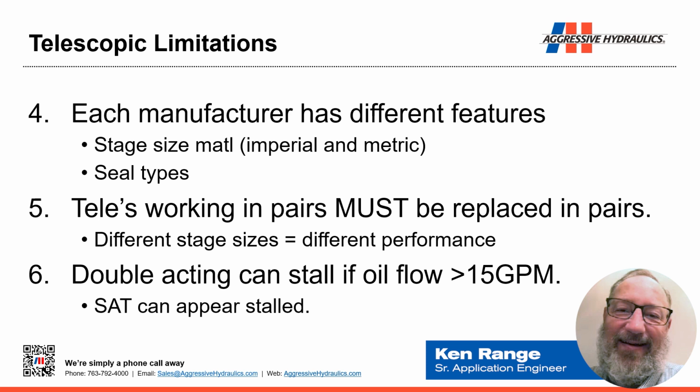It might only represent a few millimeters, but when you're talking about a very large stage size for some of the very large telescopics that are out there, that get 10, 12 inches outside diameter, just those few millimeters can result in hundreds of pounds of difference between forces. So it's very risky when you're comparing the performance of different telescopics from different manufacturers, because without having that performance chart or knowledge about the specific stage sizes, the performance can be significant.